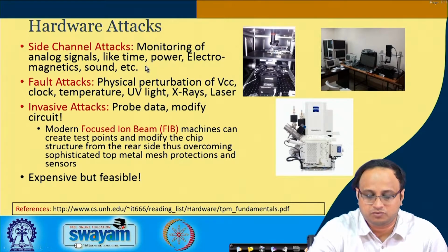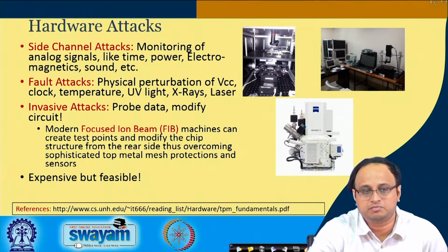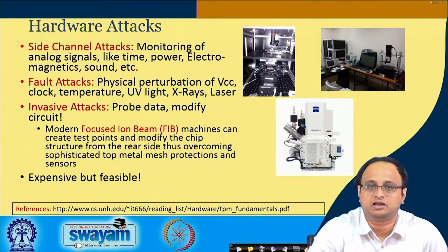Okay. So for example, you can probably appreciate this point that when you try to do traditional hardware design, you try to minimize power. But when you are trying to develop secure hardware, your objective may be rather different. Of course you have to minimize power, but what is more important is that you ensure that the power consumption doesn't vary with your inputs. Because if it varies, then the attacker can catch those variations